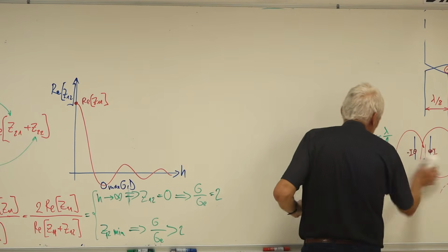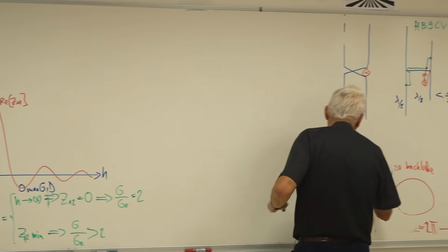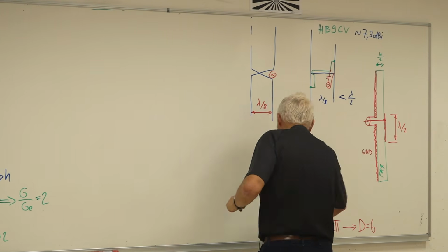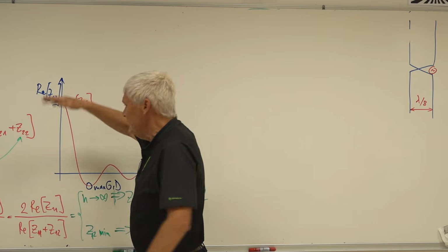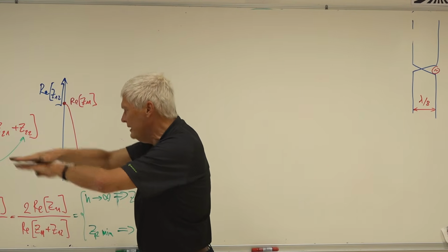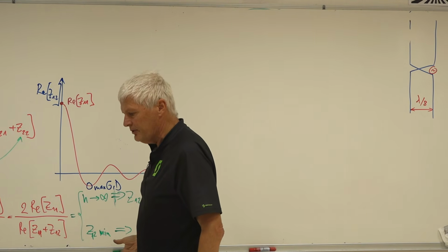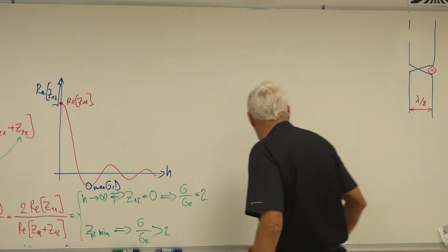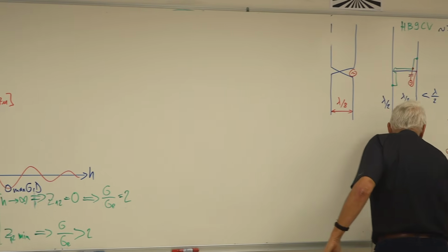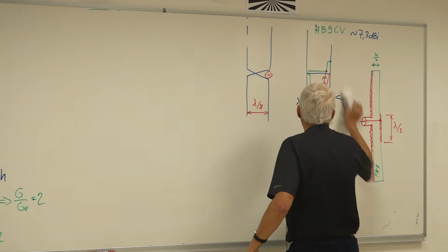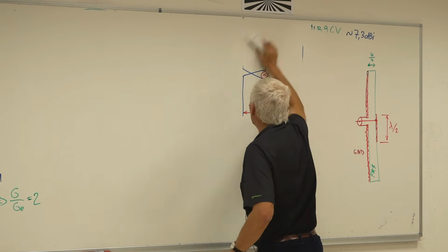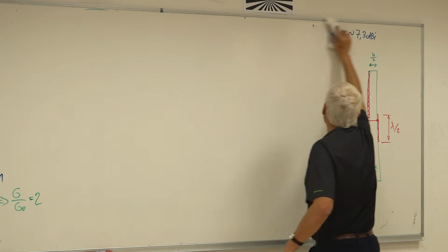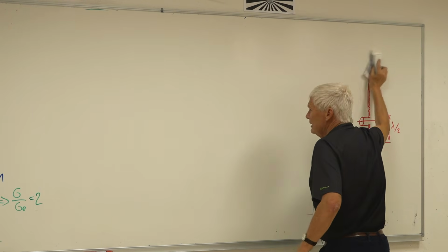So this is how things should be done to get it correctly. Of course, you see from this diagram here, because the starting point here is Z11, if you put the antennas extremely close together, you gain nothing from your array. So the other thing here is an even simpler way, yet another shortcut, but this is only approximate.